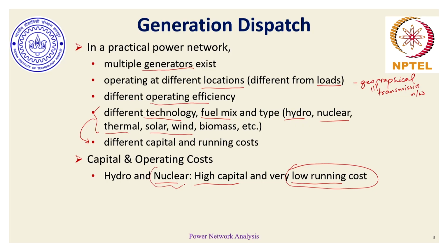The reason they act as base power plants is that controlling nuclear reactions is obviously not as easy as controlling the flow of steam or water through the turbine to drive the prime mover or the generator. So from the control and safety operation perspective, nuclear power plants tend to behave as base power plants. And if an element is operating at the same quantum of power, most likely its wear and tear would be lesser, so maintenance cost would be lesser and hence operational cost would be lesser.